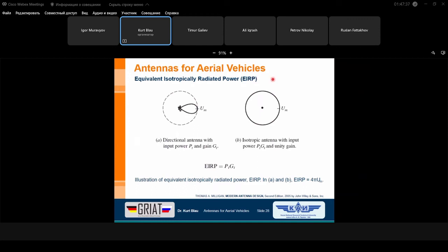But I know from our students in Germany, to bridge the distance to the access point with high reliability, they also used antennas with a gain of 10 dBi or so, and it's clear that then you have a better signal to noise ratio or signal to noise behavior.